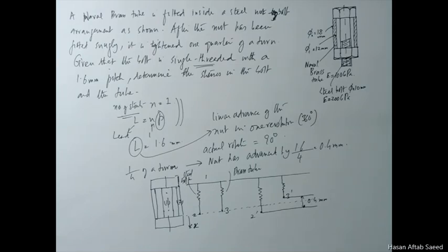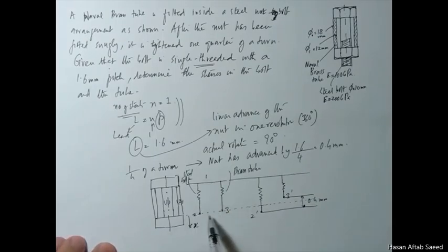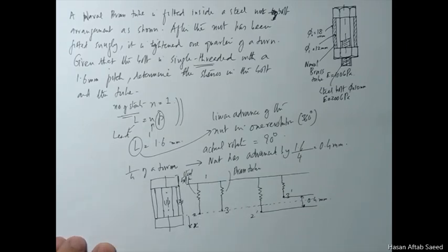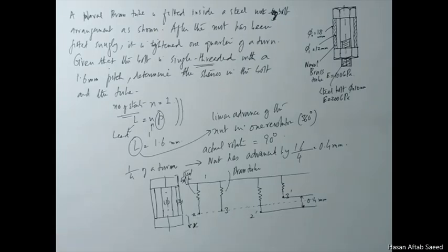So it's not that kind of a problem in which you have this one node and you have this two node which is the same, and then whatever happens to 2 also happens to 3, so you have the same boundary condition. No, 2 and 3 are linked in a certain sense, but they are not. First of all, we don't know the value of u2, we don't know the value of u3, but we know that displacement in 2 and the displacement in 3 add up to 0.4.